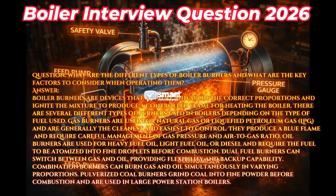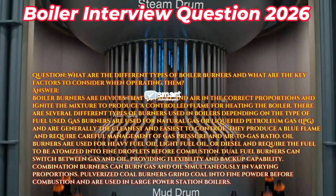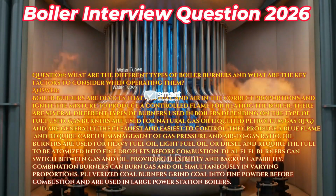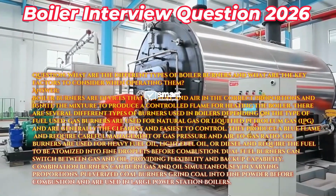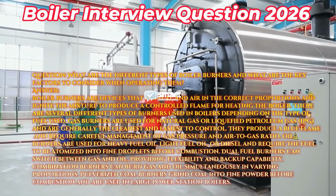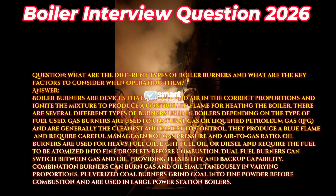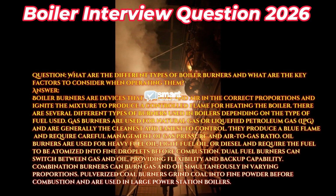Question: what are the different types of boiler burners, and what are the key factors to consider when operating them? Answer: boiler burners are devices that mix fuel and air in the correct proportions and ignite the mixture to produce a controlled flame for heating the boiler. There are several different types of burners used in boilers depending on the type of fuel used. Gas burners are used for natural gas or liquefied petroleum gas, LPG, and are generally the cleanest and easiest to control. They produce a blue flame and require careful management of gas pressure and air-to-gas ratio.